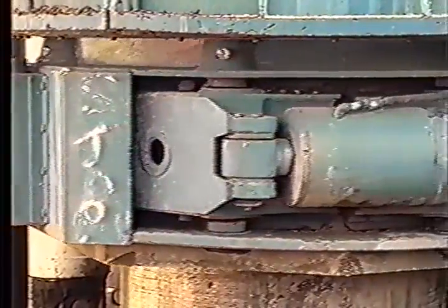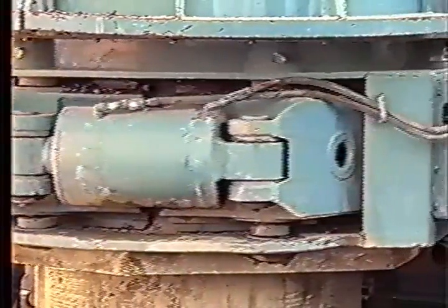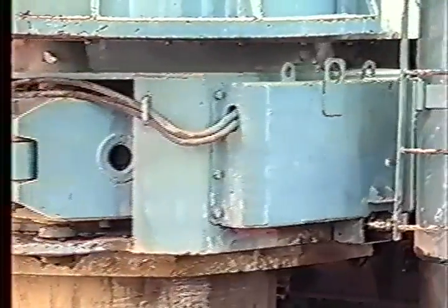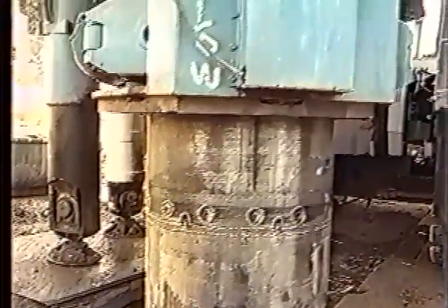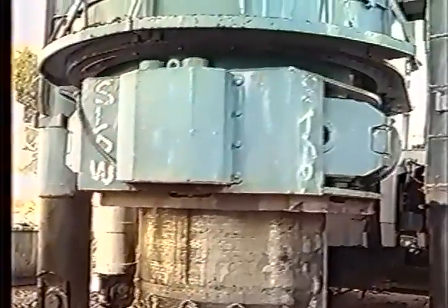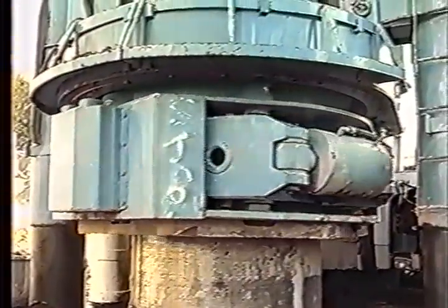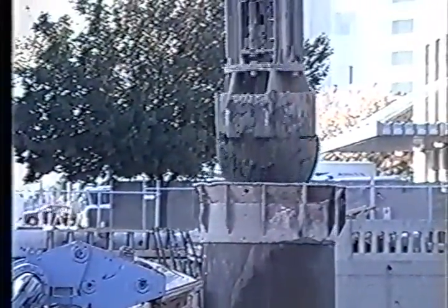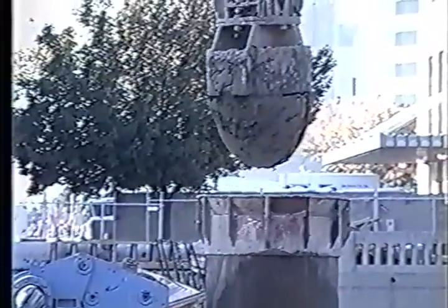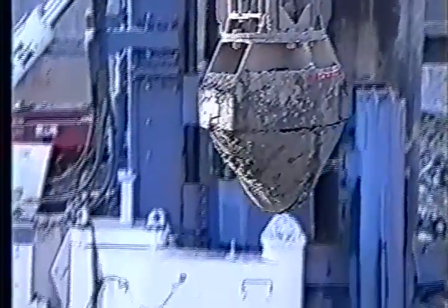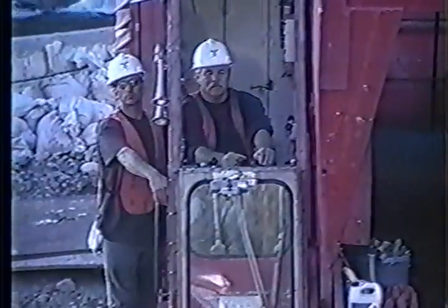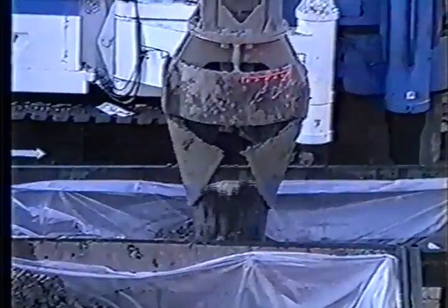The XL rotator makes easy work advancing the casing ahead of the excavation. A cutting shoe with drill teeth is attached to the bottom section of the casing. With 1,250,000 foot-pounds of torque, the rotator pushes the casing steadily down into the ground. The large-size grabs excavate the contaminated spoil. The spoils are placed in a lined dumpster before being removed for disposal.